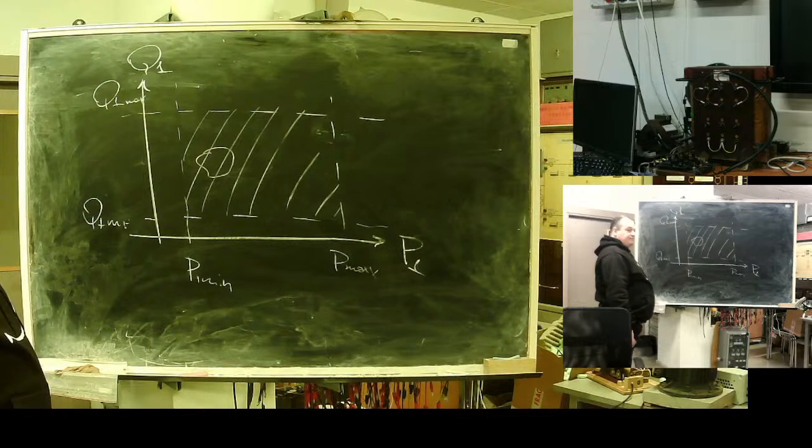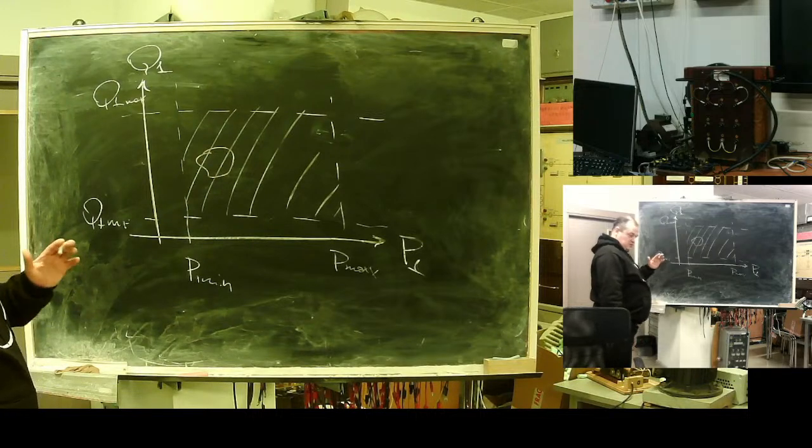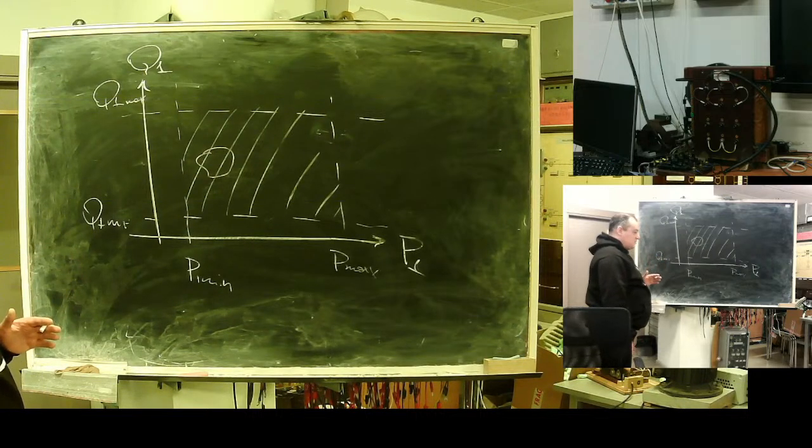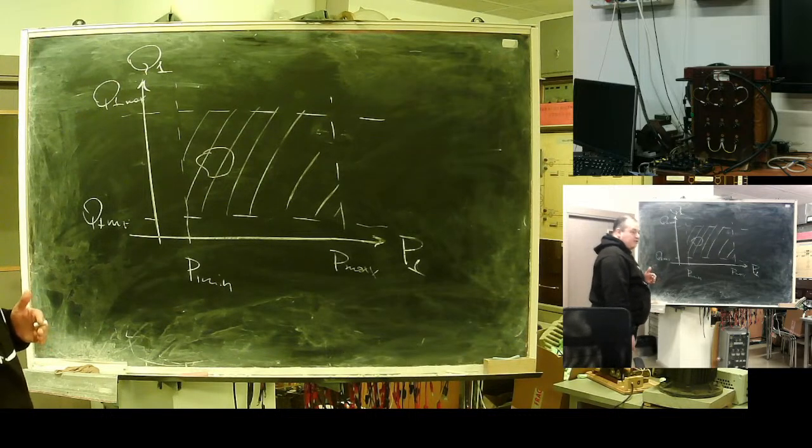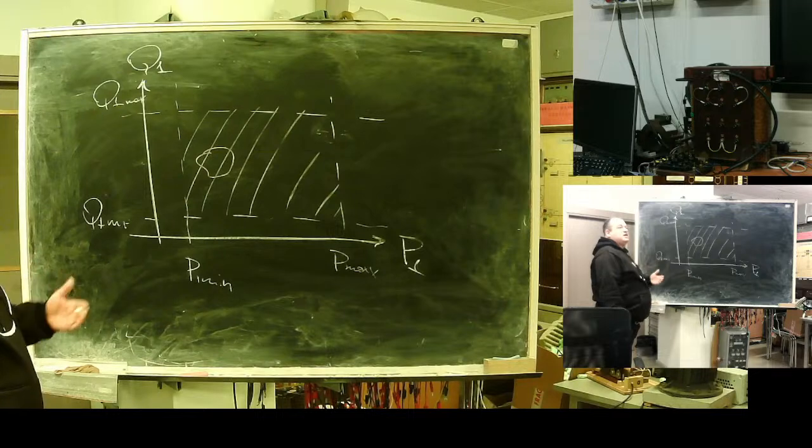The same condition applies to the transmission line, but for some countries or regions, a very painful moment is air temperature, because air temperature sets the possible current limits for the transmission line. So a less effective mode should be selected to avoid overheating of the line. It's not our problem. We don't face the line overheating problem.